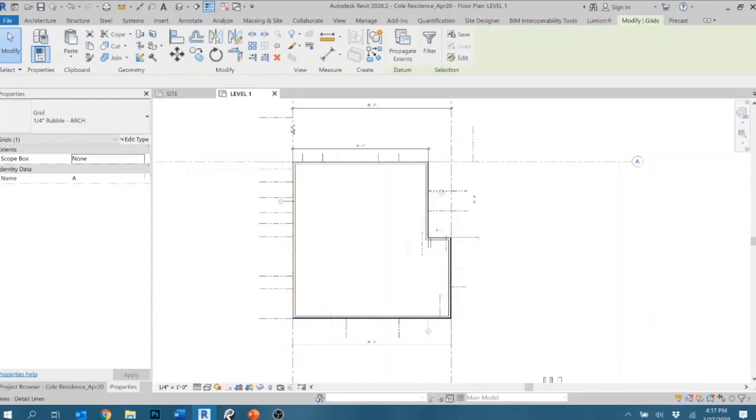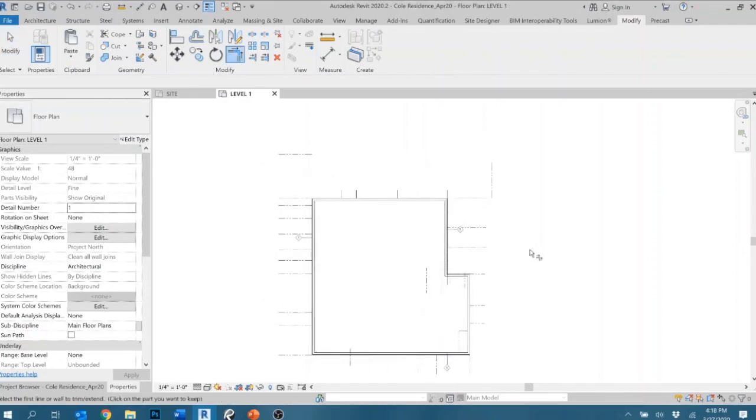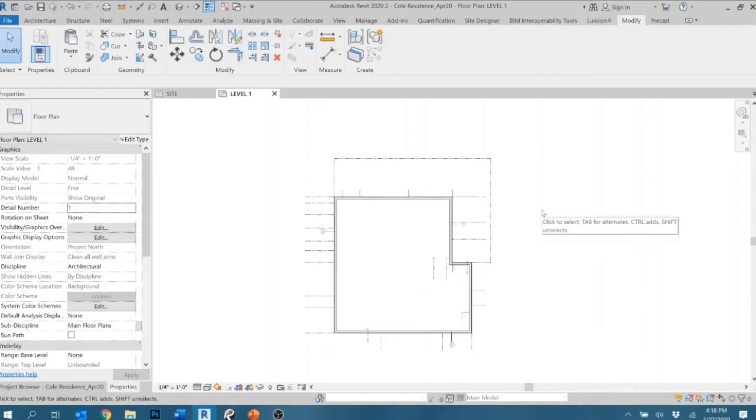element, or selecting them all and typing in element hide. We can now place doors and windows in our plan. But first, let's trim some of the detail lines so that they make a little more sense. I typed in TR for trim. I'm going to touch the elements. I'm trying to draw the porch right now that I want to remain. I want this side of the trim to remain and this side of the trim to remain. Same here. Now that represents my porch. I can draw a floor in a minute.